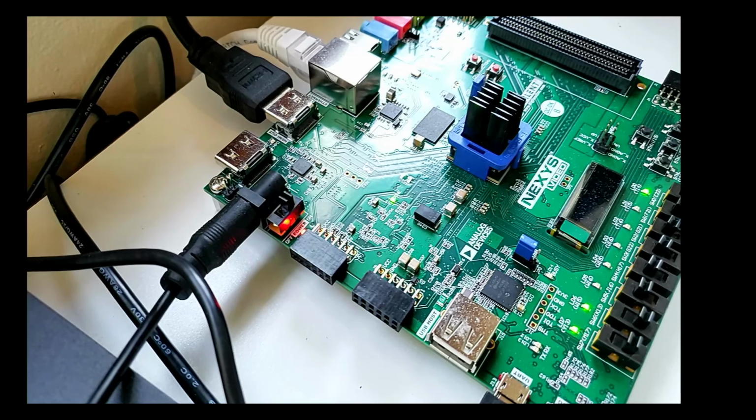So we use FPGAs when we know we don't necessarily need bleeding edge speed. This is running at 100 megahertz. You can get certain designs up to 300 megahertz. You almost never see anything faster than that for an FPGA design. And it's great as a teaching tool as well, right? Or as a research tool.